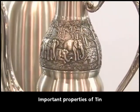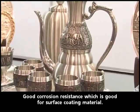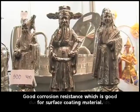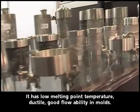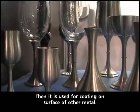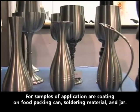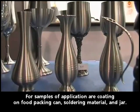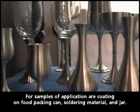Important properties of tin. Good corrosion resistance, which is good for surface coating material. It has a low melting point, is ductile, and has good flowability in molds. Then it is used for coating on the surface of other metal. Examples of application are coating on food packing cans, soldering material, and jars.